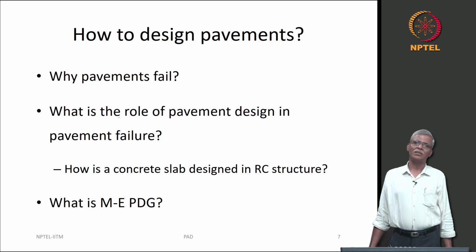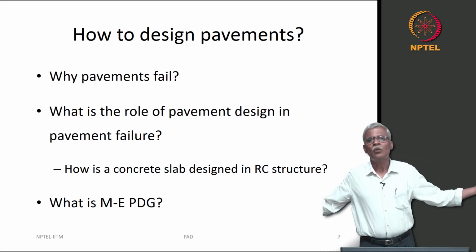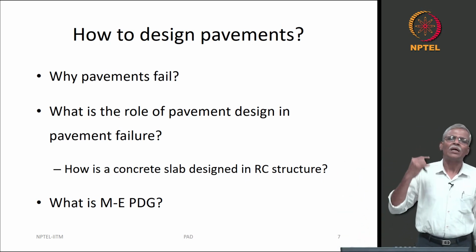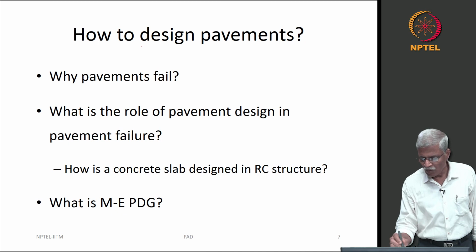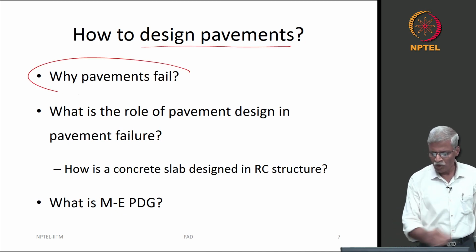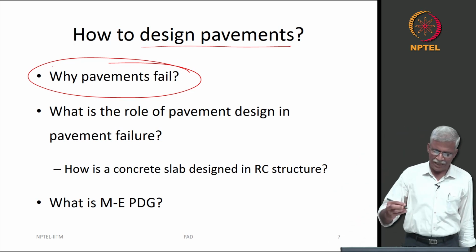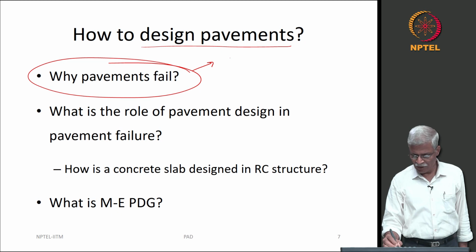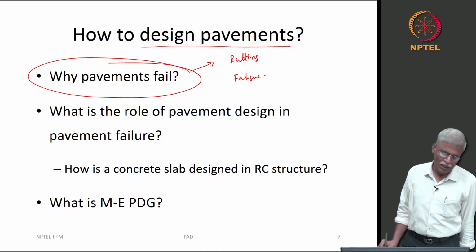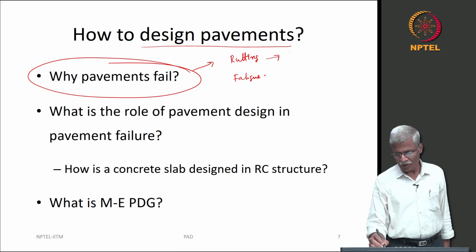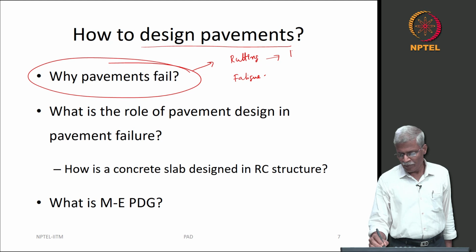So, now let us ask some basic questions. How do you design a pavement, okay? As I mentioned before I start talking about how do I design a pavement, what I really want to ask is why do the pavements fail? Basically before that, you want to say how do the pavements fail? So, you are going to say that oh, the pavements can fail due to rutting or fatigue. Now, why do the pavements fail like this? So, then you can talk in terms of high temperature,